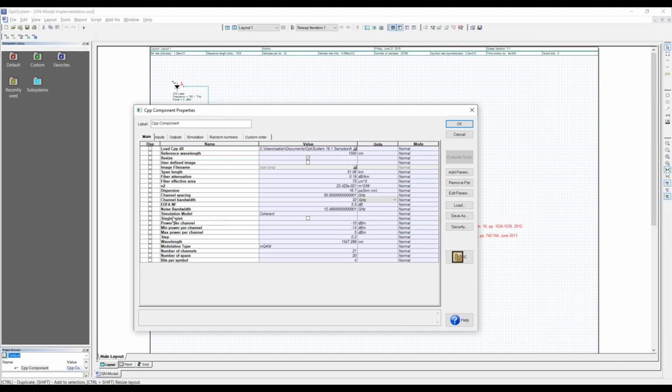And here is the concept of calculation. We have two models here, coherent, as we explained before, and incoherent. So you choose the way you want to calculate, coherent or incoherent. You can calculate a single point or multiple points in the calculation. This is especially for the bit error rate calculation, if you want to scan through a range of power levels. For example, here we scan from a maximum power level of 5 dBm to minus 14 dBm.